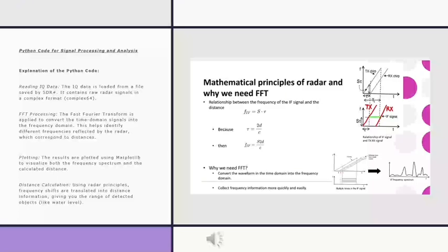We use the chirp signal in our project. We send that, and after that signal hits an object and bounces back, we use the antenna to receive that signal. Once we do some signal processing, such as differentiation of that chirp signal, we can get a constant frequency signal line, which is the green line on the graph. That frequency is only related to the distance between the object and water level. So once we find the frequency of that green line, we can find the distance between the object and the radar.